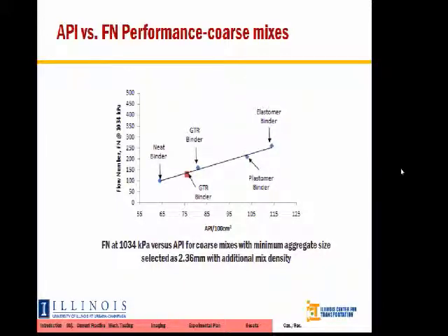And obviously, we drop to a slightly lower flow number when we compare the original GTR specimens to one of a slightly lower density or higher air voids. Okay? But it also reduced the API. So we are affecting the internal aggregate structure, but we're still able to quantify it, and it still fits the same relationship that was determined.